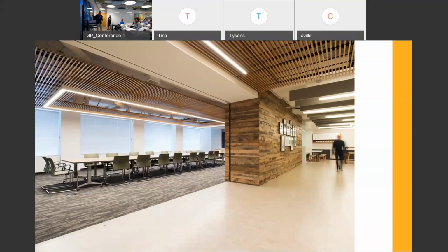Another challenging space here is coming into a lobby, an elevator lobby, and you have 3 spaces that you need to blend in together around your architecture. So we need to make sure we've got 3 different type fixtures, same concept, but you've got to make sure that they're all the same color temperature because the architecture is all the same. It didn't change. So it doesn't necessarily mean you have the same manufacturer, but you've got to make sure that their color temperatures match. If you don't want this side of the wall looking different from that side of the wall from a different perspective.